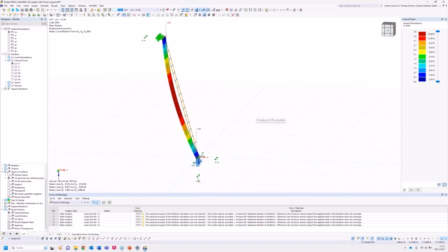Why? We have now double force in vertical direction per support. Means also double the allowable force due to friction. And that's why it always helps when someone stays at the first step if the other one is going higher. So then we can go into our next model.